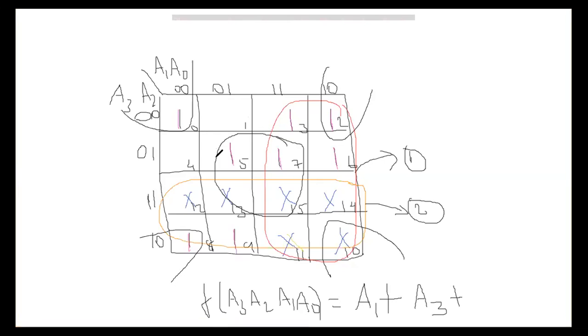Now I'm taking these 4 box combinations. These are the 4 box combination, take it as a 3, and the corner bits is a 4. For this 4 box combination, you can see correspondingly 0, 1, 1, 1, 0, 1, 1, 1. A1 changes. You see here, A1 is a 0 here and A1 is a 1 here. So A1 is ignored. Only I am taking the A0. So A0.